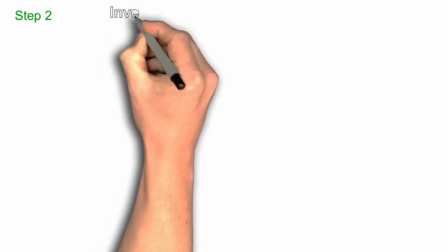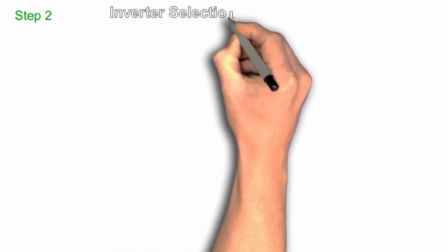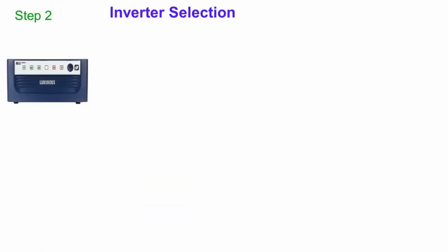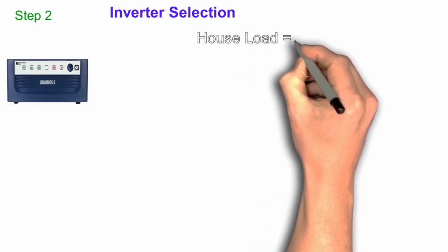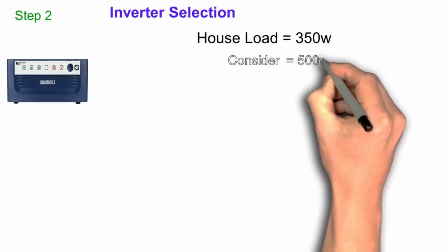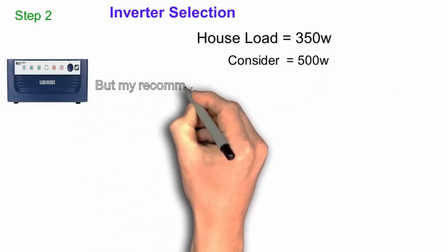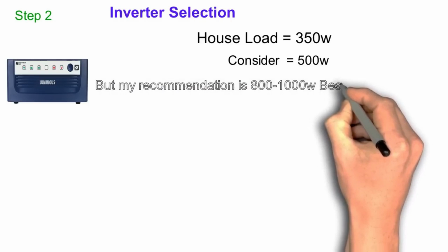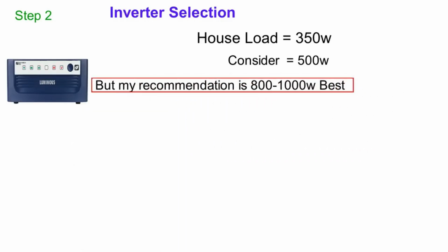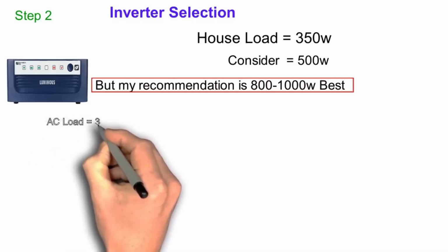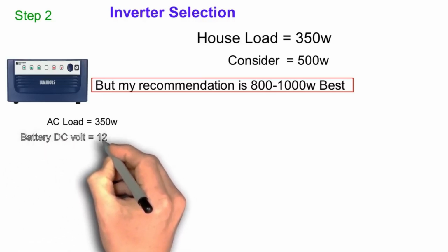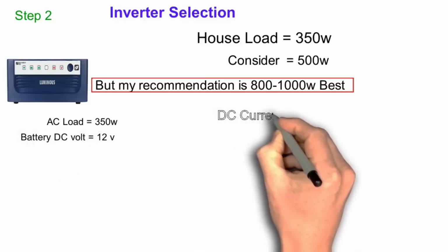Next, we move on to battery size selection. If you want to store energy for use at night or during cloudy days, you'll need a battery bank. To calculate the size of your battery, you'll need to know your daily energy consumption and how long you want to run your appliances on battery power alone. For instance, if your daily consumption is around 10 kWh and you want to run your system for 2 days without sun, you'd need a battery bank that can provide at least 20 kWh of stored energy. It's important to select a battery with a capacity that meets your backup needs but also takes into account the efficiency loss.